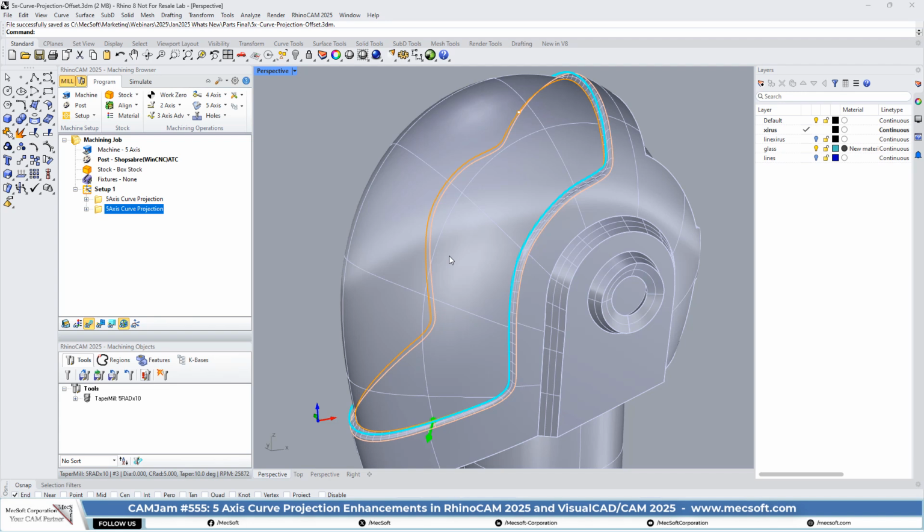Just put that half-finished punched part on a fixture, and you can use this toolpath to go around and clean up those edges. In fact, they use this a lot with robotics to go ahead and cut and trim things in 5-axis. In this particular example, it's a straightforward 5-axis continuous toolpath. In our 5-axis menu, it is the curve projection method. Now, in curve projection, this is a go-to operation type for cleaning up areas around edges in 5-axis.